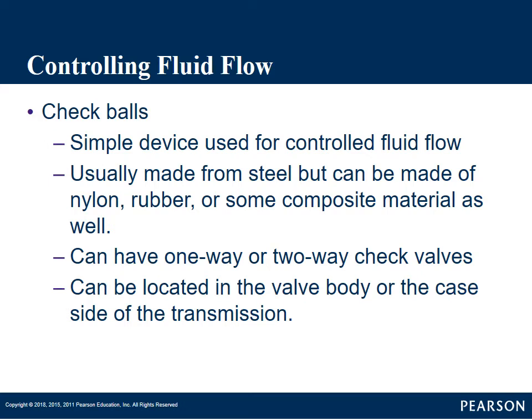Okay. These check balls can be one-way or two-way check valves or check balls. They can be located in the valve body or the case side of the transmission. Somewhere in those passages, you'll see a valve body, and many times what they're blocking or opening up are holes in the separator plate. If you remember, that separator plate goes between the valve body and the case.